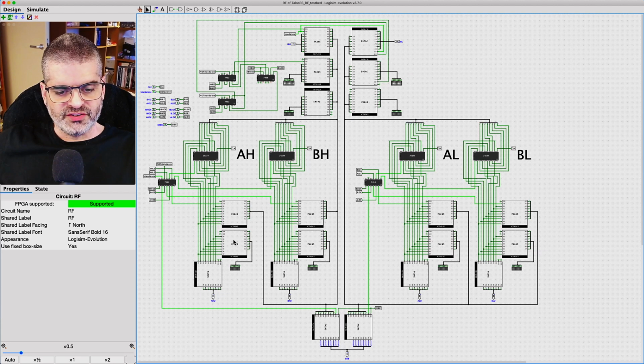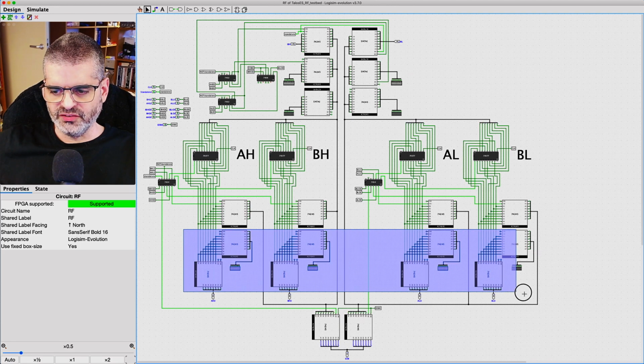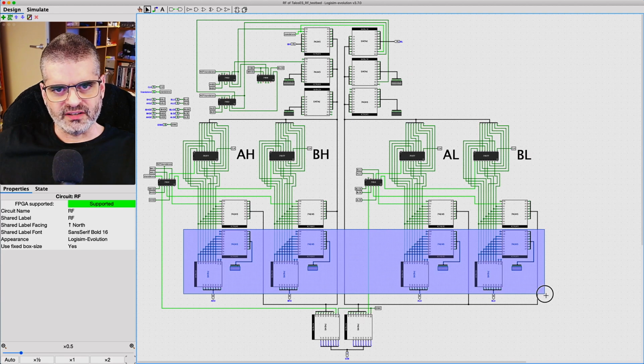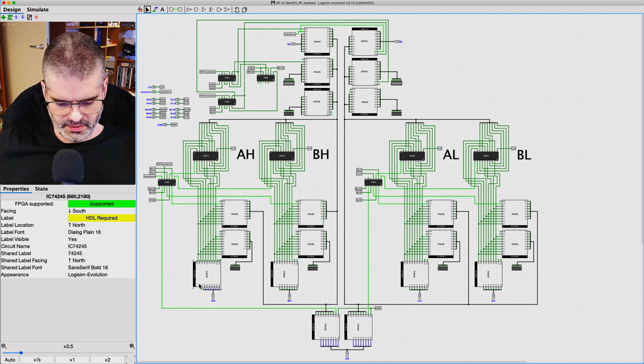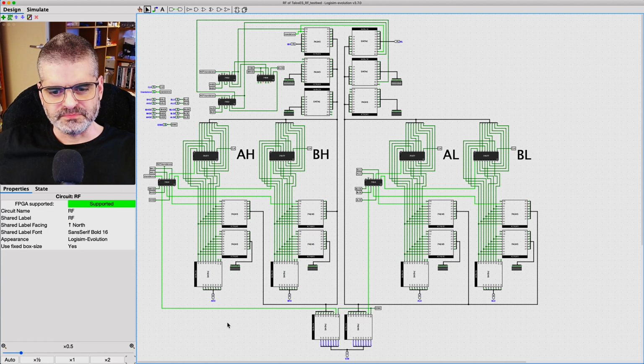The LED drivers are also continuously enabled. Output enable is grounded and direction is grounded, so it's always from B to A, so it's always to drive the LEDs. So what I just said accounts for these 8 buffers here. They are just to drive the LEDs and to drive the register values to the ALU board bypassing the internal bus.